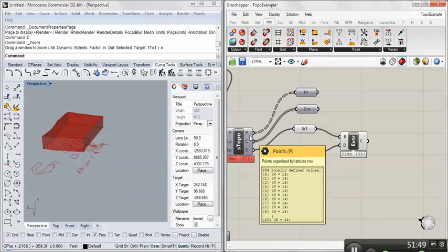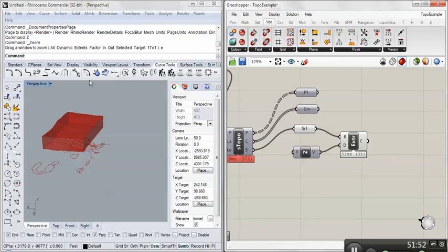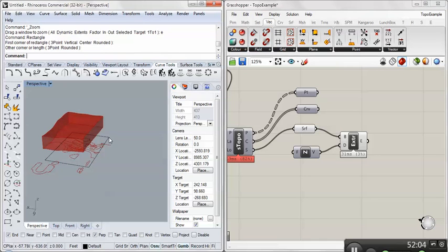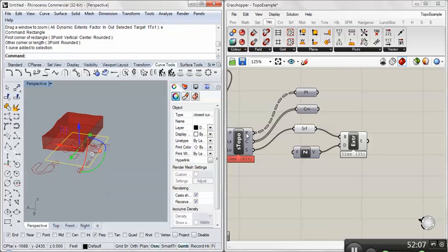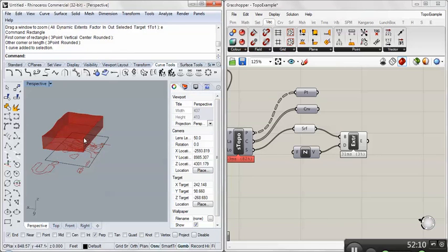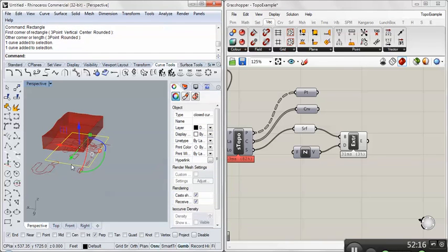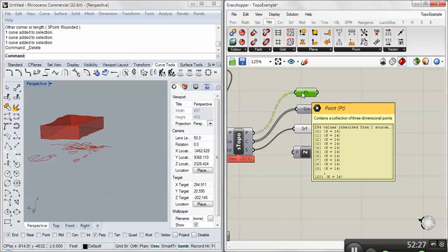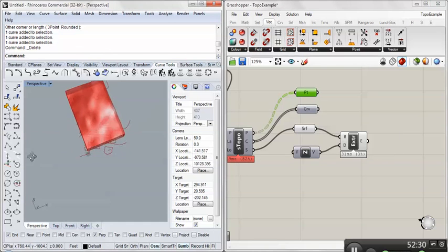The trick there is, the loft is just going to give you the edges. So say we made a rectangle down here. Is this kind of what you were thinking? Rectangle there, loft that to the perimeter of this. Right, because if you're going to CNC that, I guess you'd want a flat base. Yep. So yeah, we're going to make the flat base. The only reason I didn't do the loft is it's a little weird. Well, we can do it that way. That's fine. That works easy too. So we'll do that.